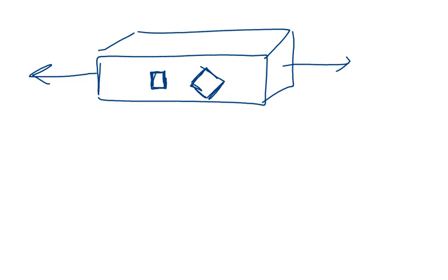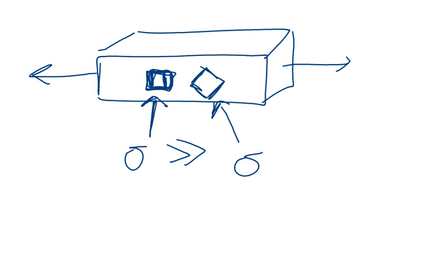And in fact, if you need another reason, the stress that you measure when everything is lined up correctly is going to be the largest stress. This normal stress is much larger than the normal stress that you would measure if you were using a different set of coordinate axes.